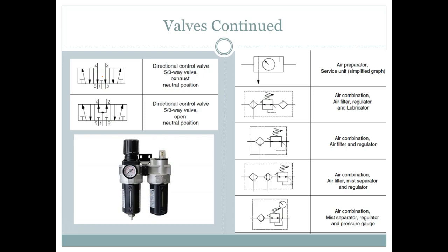What's a safety release valve? If you get too much pressure, if you get to a dangerous point, it vents everything, right? You understand? And we run that on compressors too. So on our compressors, if something goes wrong with our regulator or my upper limit switch, I think they showed it on Mythbusters one time, where they actually defeated the pressure relief valve and the pressure regulator, and they let that compressor just build up pressure. What happened? It blew it up.